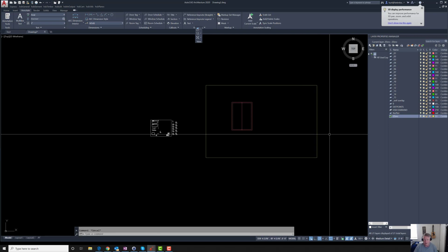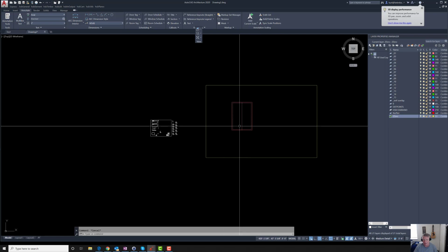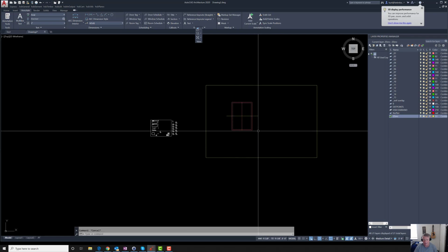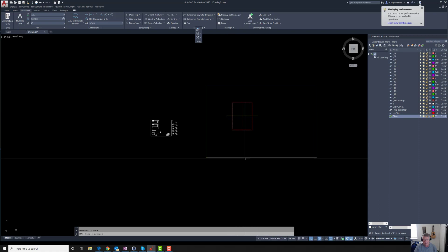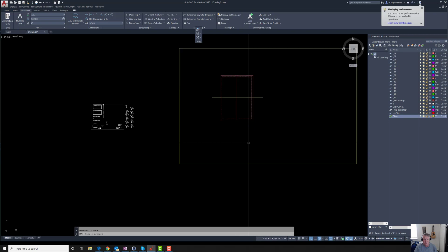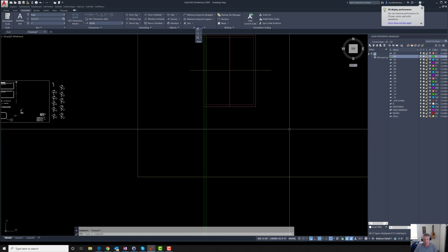So you'll see what I mean here relatively quickly, in that I'm going to start drawing a section cut, and we'll just imagine the cut being right through the middle here where there's no hips or anything like that. I'm going to draw that section cut where the floor is, this line right here. So I'll start doing that by dropping some construction lines. I'm going to change to a different layer so we can keep things straight, and I'm going to drop some construction lines down at really just the wall line and the overhang fascia line.